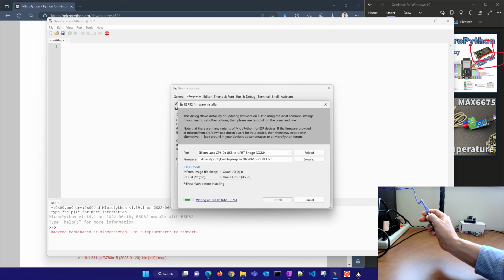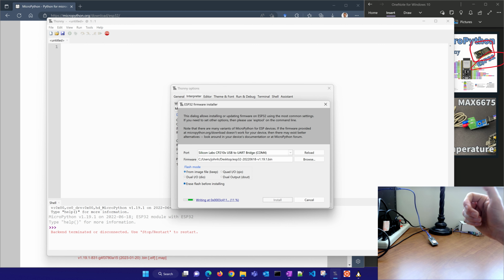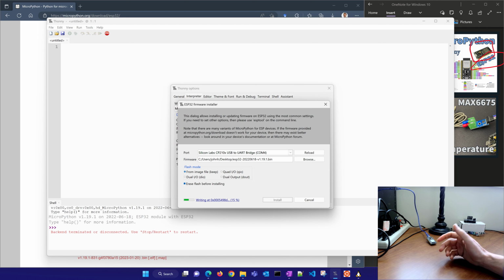Okay, now you can see it start to write. Now I'm just going to release that, and it should be able to finish all the way. But just hold that boot button down. I've tried before where I just touch the button and then release it, and it has an error that it can't connect. So I just hold that boot button down until it gets into this mode right here, and you can see it's writing the firmware. You can see little flashes occasionally just as it's going.